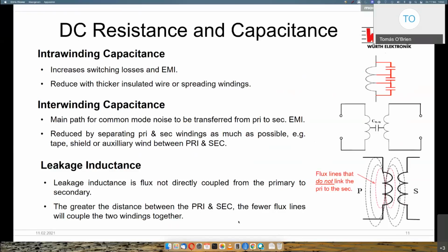The leakage is a big problem because, one, it's lost, it's a waste of energy. We need a snubber to usually clamp the voltage so we don't have issues with our MOSFET. And that snubber just wastes energy, it gets hot, but still we need to do something about it. So ideally, it's better if we can do something about it in the transformer, so we don't have to have such big snubbers and waste so much energy.